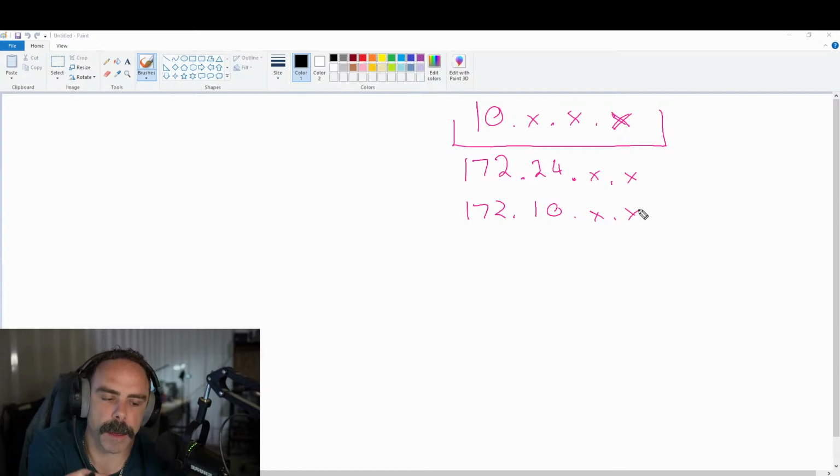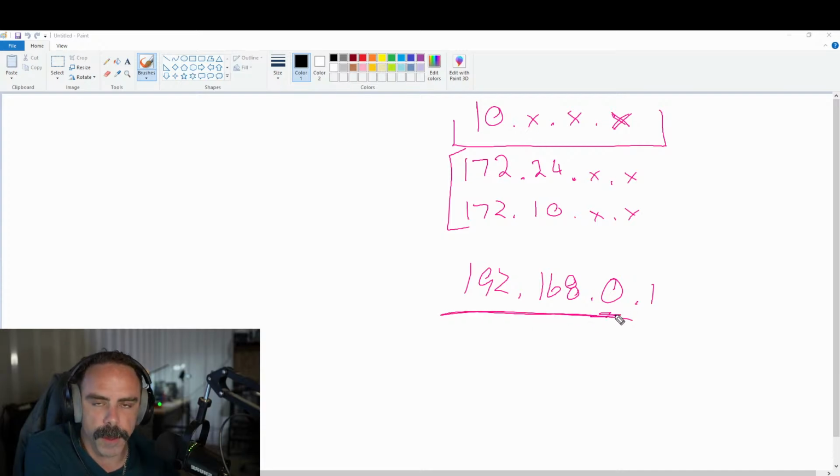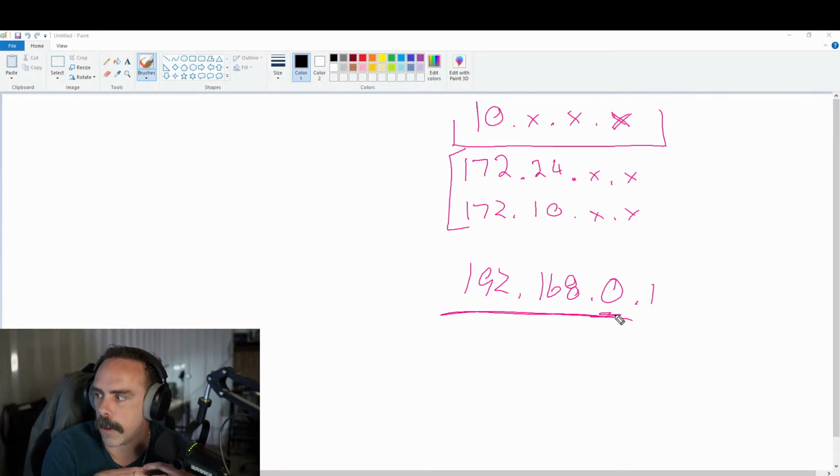And here's one thing that I like to do, and I like to use these less commonly used subnets, is I don't like using the 192.168, especially the 0, because you have so many devices that if you just put a device on their default address, it might conflict with something on your network. And so I almost never use this 168.0, because if someone plugs in something randomly into your OT network, just trying to figure out what's going on, that default address might step on something important, and so you would never want to do that.